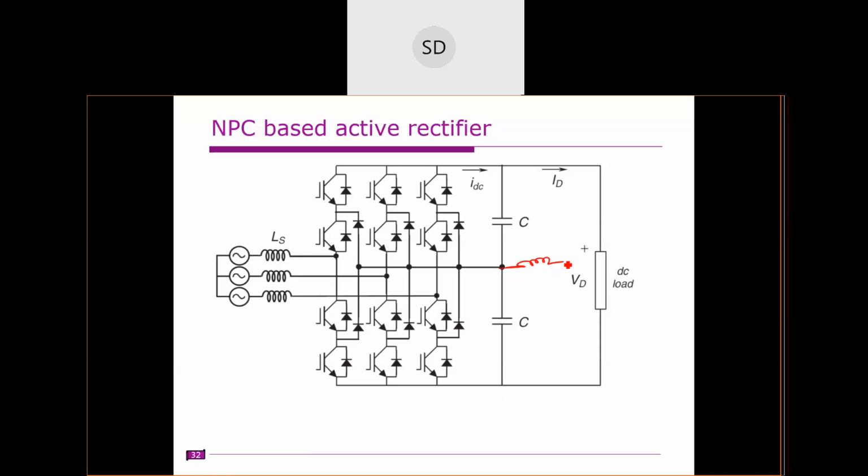So this is the additional circuit. We need to connect a switch here. We discussed this, right? And another switch. The sole purpose of these two switches is to balance these two capacitor voltages. To balance these two capacitor voltages, you require this kind of external arrangement.